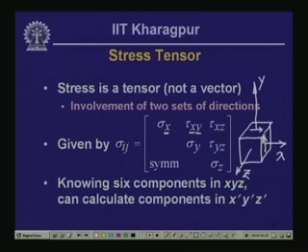And you notice that as soon as the shear stress was occurring on the top horizontal plane, we introduced another shear stress occurring on the right vertical plane, and similarly you are going to have 2 more shear stresses on the 2 planes that are not visible from the front.